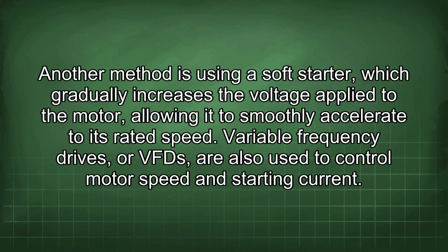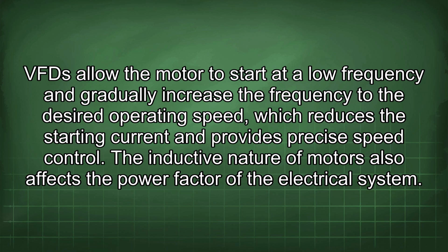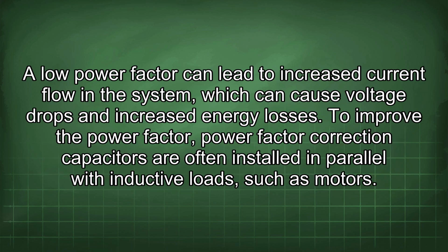Variable frequency drives, or VFDs, are also used to control motor speed and starting current. VFDs allow the motor to start at a low frequency and gradually increase the frequency to the desired operating speed, which reduces the starting current and provides precise speed control. The inductive nature of motors also affects the power factor of the electrical system. A low power factor can lead to increased current flow in the system, which can cause voltage drops and increased energy losses. To improve the power factor, correction capacitors are often installed in parallel with inductive loads, such as motors.